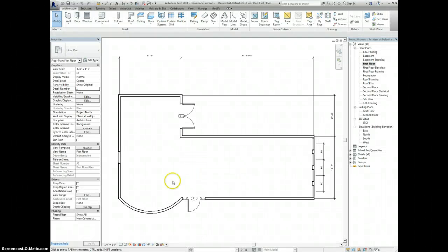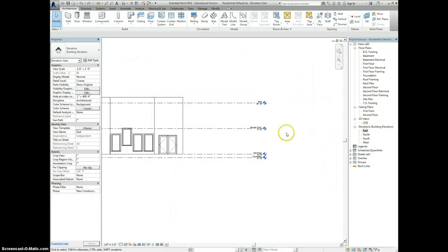So where we last left off, we talked about how to add walls, how to add windows and doors, and how to set things equal to each other. And I want to show how to create roofs, but before we do that, we have to set up elevations or levels. And if you look up here where it says datum, you don't have the option for a level. That's because in order to do this, you have to be on one of your elevation views. So let's open up, let's say the east floor.